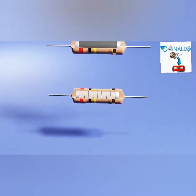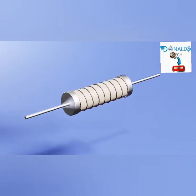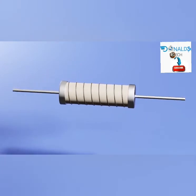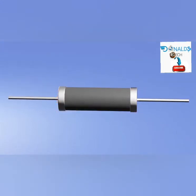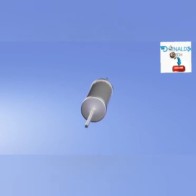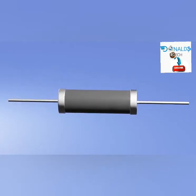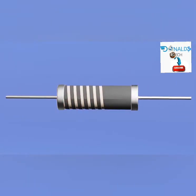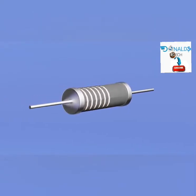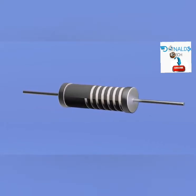The first way is using a nickel wire wound in a ceramic tube, which by the way is an insulator. In this way, you can control the total resistance by modifying the length of the cable, but maintaining a compact size. The second option is using a composite material in a defined volume, but by varying the elements that make it up, you can vary its coefficient of resistance, and therefore the resistance of the resistor. And the third option is by means of a ceramic cylinder covered by a carbon film, which is cut in a spiral until obtaining the desired resistance. In other words, a carbon wire is gradually created to increase the resistance to the desired value.